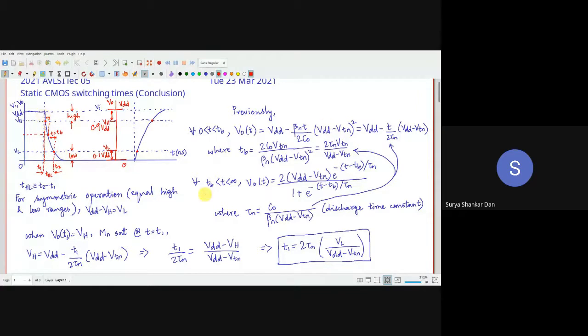Okay, we are trying to find out the exact variation of this. Remember, these equations are what run in your Cadence, but they solve it by numerical methods. We are doing it analytically, so we are excluding some of the finest details. Cadence will take care of all the finer details of the device. For example, here, if you notice, this is the current in the saturation region, so there is this 1 plus lambda VDS term missing, right?